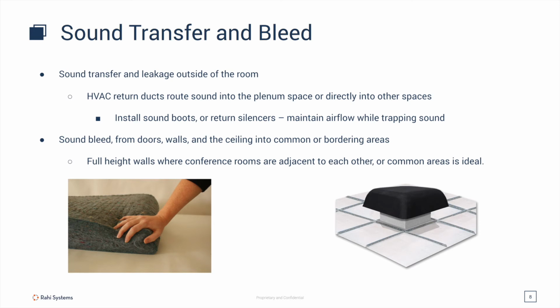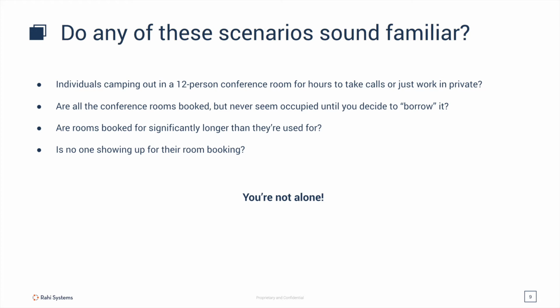Unfortunately, rooms that make great meeting spaces also have a high probability of being acoustically challenging. Multiple glass walls, hard surfaces like concrete or whiteboards are all considered reflective surfaces for audio. Some common solutions for reflective rooms are to use ceiling tiles that have a higher sound absorption rating, installing baffles or acoustic wall panels, or some sort of floor treatment, minimally carpet instead of polished concrete. Solving for the issues above will help maximize your return on investment for the equipment you purchase for a video conference room.